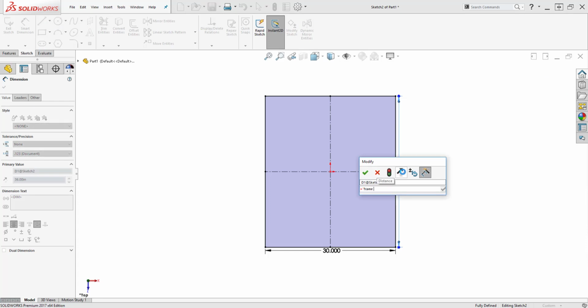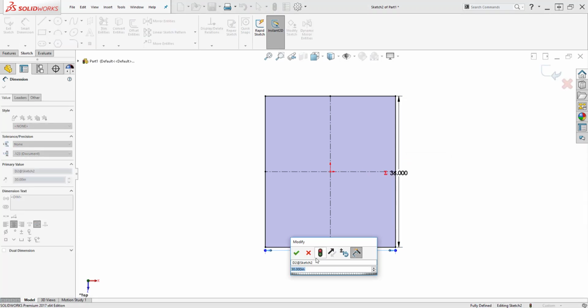When you do this in actuality, you might want to take off about ½ an inch for the max frame perimeter on each side, so the inspectors are going to pass your frame easier when you get to competition. This also gives you some tolerance with frame perimeter when designing mechanisms for the game.